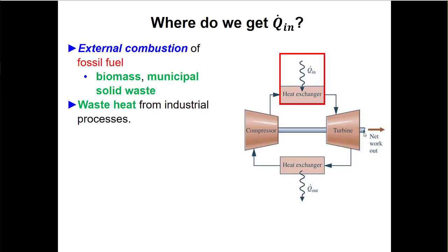And remember, we talked about one of the downsides to the efficiency of a Rankine cycle is that cooling that steam down to a liquid means that you're removing a lot of heat. But just like when we talked about in the textbook, when we were talking about ideal cycles and stacking them on top of each other, if we use the waste heat from something like a Rankine cycle and put that into a Brayton cycle, then we're wasting less of the heat, because some of it will be turned into work, right? We call that cogeneration. That's beyond the scope of the class, but you can read about it in the textbook.